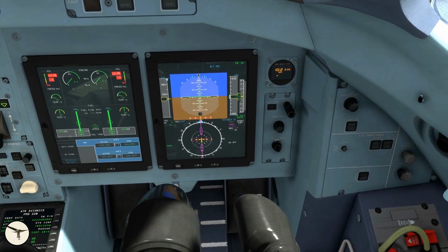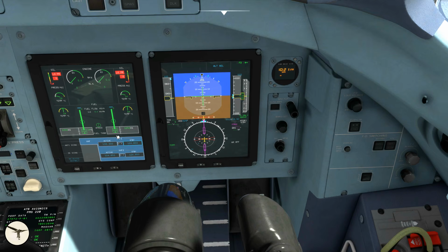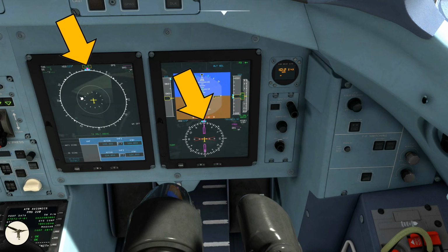On the right instrument panel we check the clock time. On the PFD we check there are no flags and that the altitude is correct. We cross-check the heading indication on the HSI and the navigation display. If you don't see the navigation display, click in this area on the screen. The memo panel will show the status of the cabin signs, no device and seat belts.